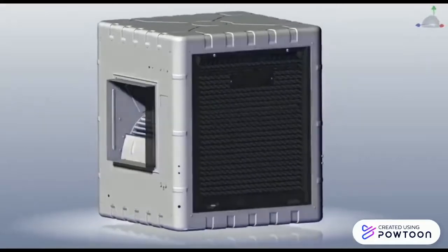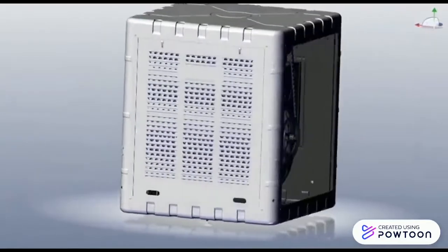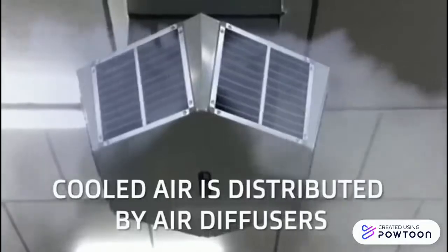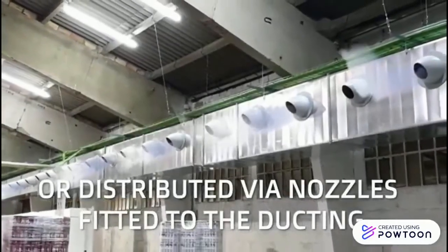This is the 3D model of our evaporative cooler. The moving animation shows the blower rotating to create a negative pressure to allow the outside air to flow into the evaporative cooler. This blower is designed such that it is able to push the air through the ducts. The cool air is then distributed by air diffusers, or via nozzles, fitted to the ducting.